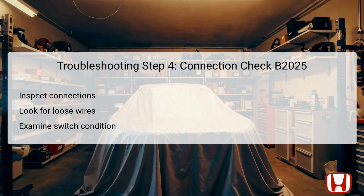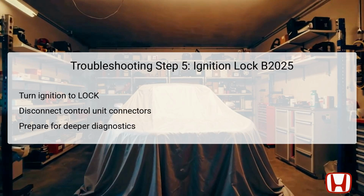If the connections are secure and the switch appears functional, additional testing will be necessary to determine the integrity of the control unit and associated wiring. After confirming persistent DTC B2025, the next step involves turning the ignition switch to the lock position to safely disconnect components. Disconnecting the left power sliding door control unit connectors A and B becomes the focus.